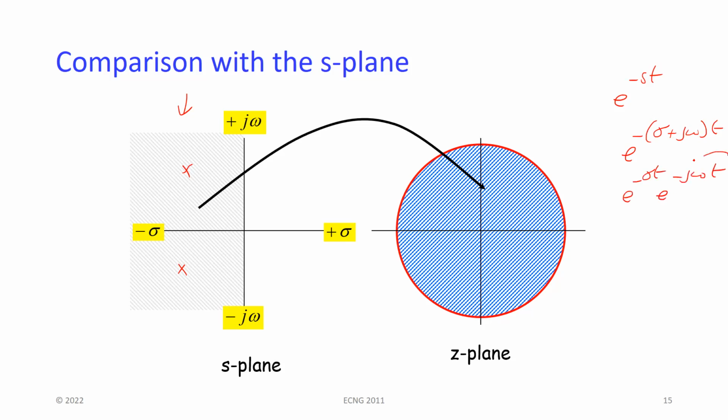This is just a complex sinusoid, so you can ignore it; it just goes up and down between positive and negative 1 maximum. For the thing to be stable, you want it on the left-hand side, because then the e to the minus sigma would make the answer converge. That would be a decaying exponential and so on.